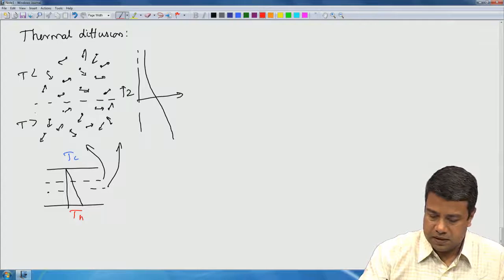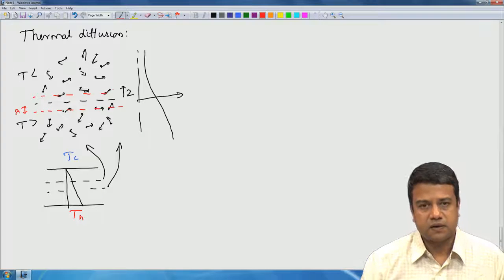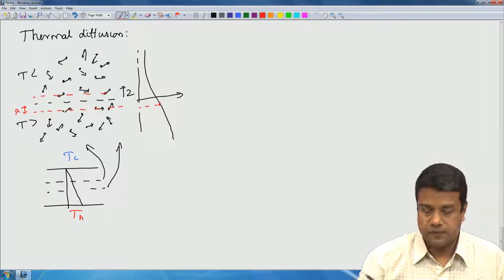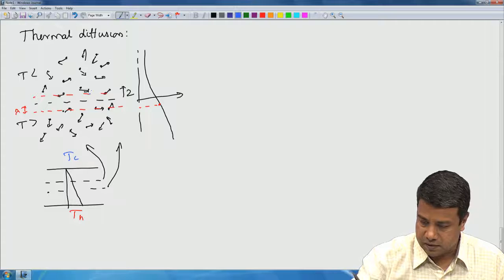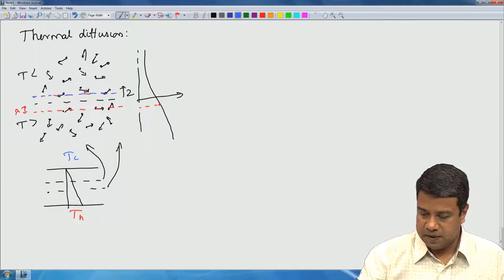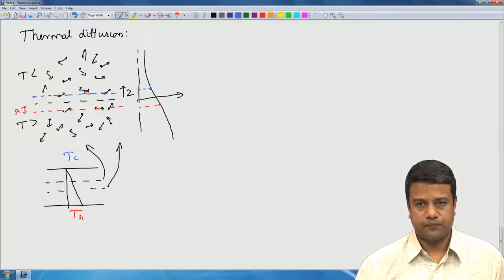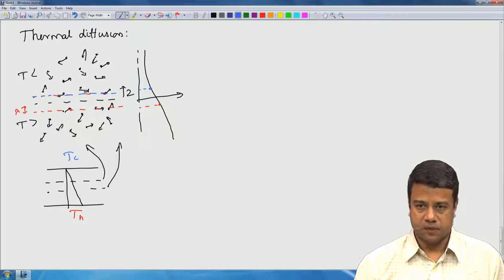Once again, the reason for this transfer of energy is because the molecules below the surface come on average from a distance of the order of the mean free path below the surface, where the temperature is higher. Whereas the molecules above the surface come from some distance above the surface where the temperature is on average lower. So, what is the heat flux due to these molecules?